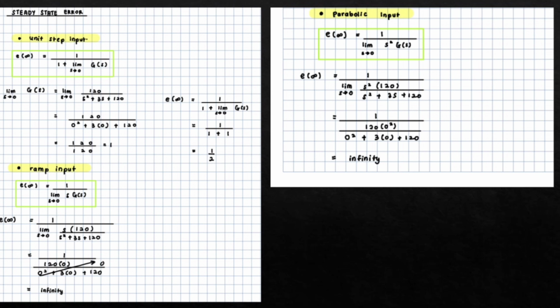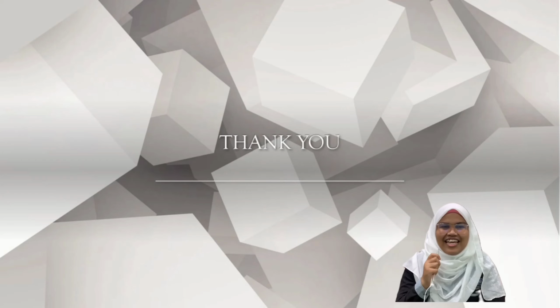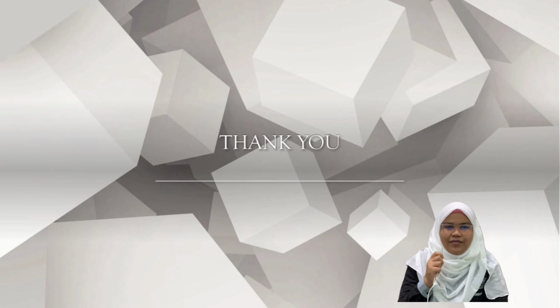The second one is ramp input. The answer is infinity. And lastly is parabolic input. The answer is also infinity. So we confirm that the system is type 0 because the steady state values fulfill the requirements, where the step input gives a constant value, and the ramp input and the parabolic input give infinity. In a nutshell, we confirm that our system is in the stable state.